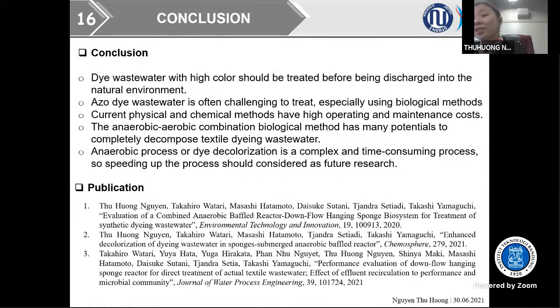However, after researching the anaerobic system for textile dyeing wastewater treatment, we found that the common challenge of azo dye anaerobic treatment includes the long processing time, because dye decolorization normally depends on other organic degradation processes, and unfortunately, it is often time consuming.